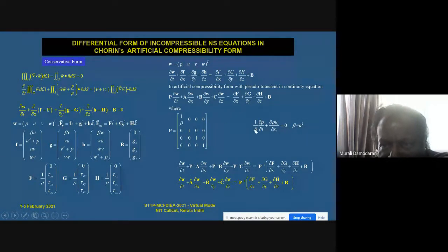And you can see as beta goes to become a large value, this term will vanish. The same idea has been developed for compressible flows. So the JST scheme in SU2, you can also use it for incompressible, steady and unsteady flow. Just one code for all speed, because you have the full range of phenomena.